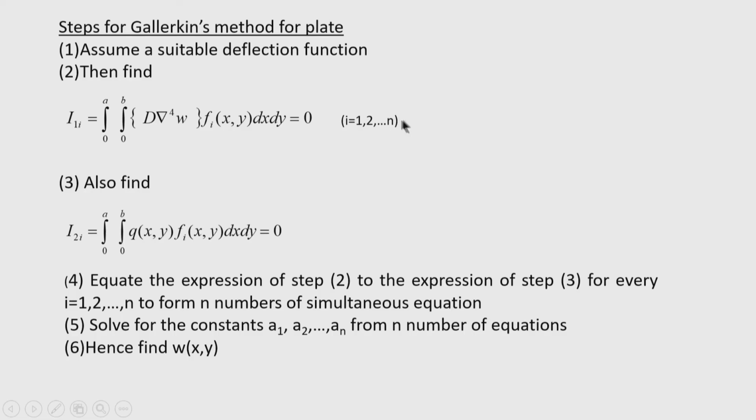For example, if I am solving a simply supported plate, with all the edges simply supported, we generally take a double trigonometrical series as the function. For example, the first term is a 1 1 sin pi x by a sin pi y by b. The second term will be a 1 2 sin pi x by a into sin 2 pi y by b. Like that the terms can be composed.